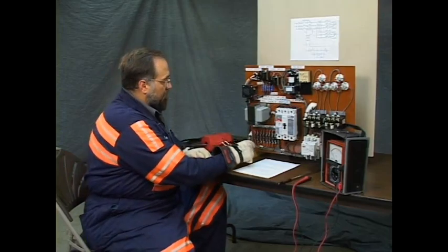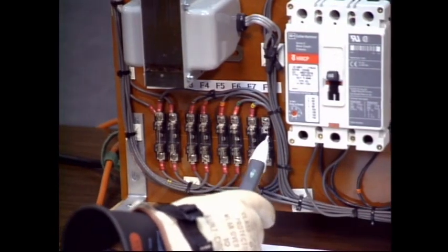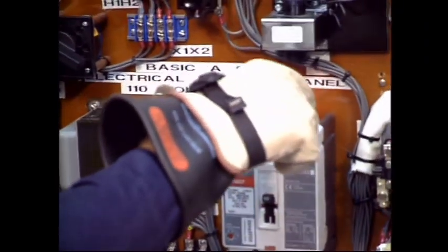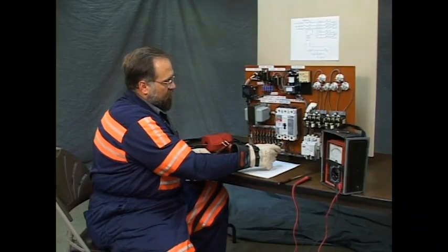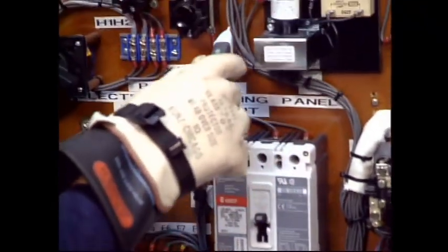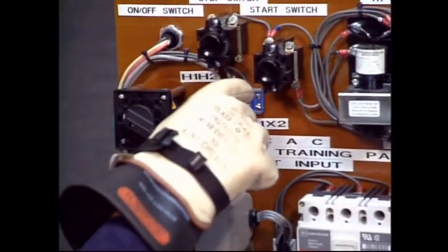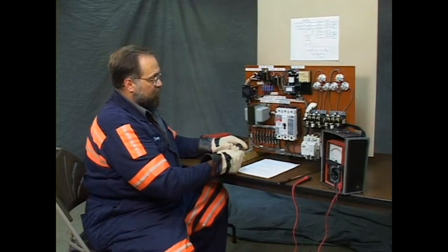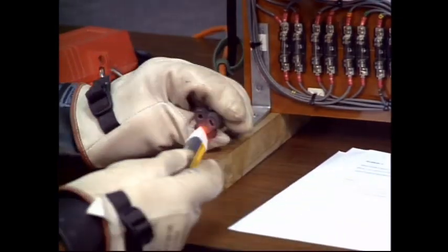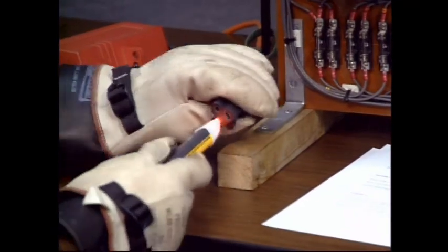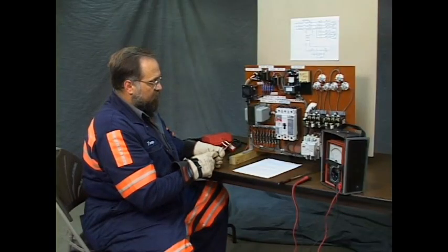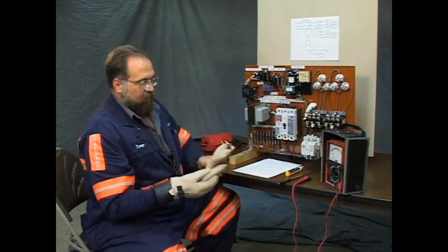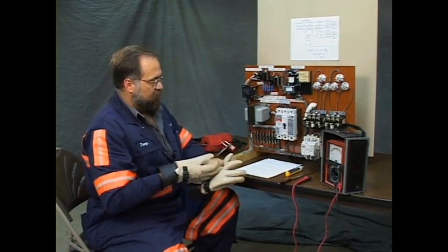Now let's see if we find any power on the board. And there doesn't appear to be any power. The little pulsing flash that you see on the tester, that's an indicator that the tester is working. When it senses power, as you probably note, you hear an audible tone and see a constant light. We're not finding that on the board. I'm going to turn that off. We can take the gloves off now that we're safe. We have no power.